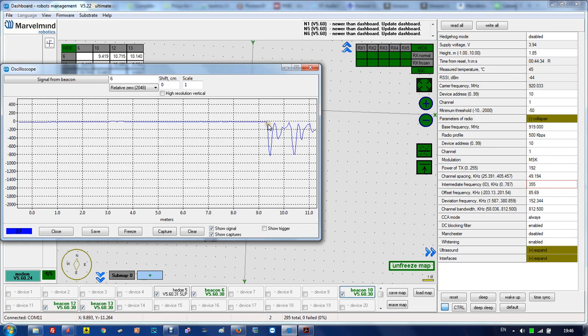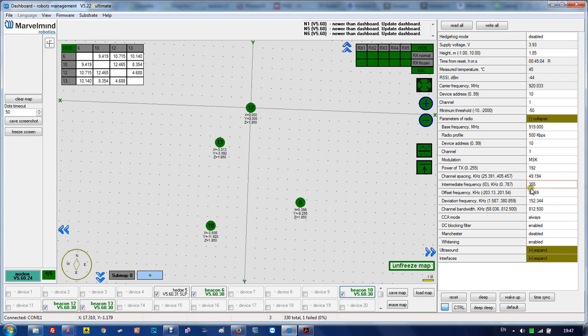But when you have too high noise, it will be amplified, and the signal may be too strong, and the signal is saturating, and the signal-to-noise ratio will be poor. And the solution is to reduce the gain. In this case, both signal and noise will be reduced, but the signal-to-noise ratio will be improved, because the noise will be reduced, but the signal will not be saturated anymore. So it means the signal-to-noise ratio will be better. So play with this.